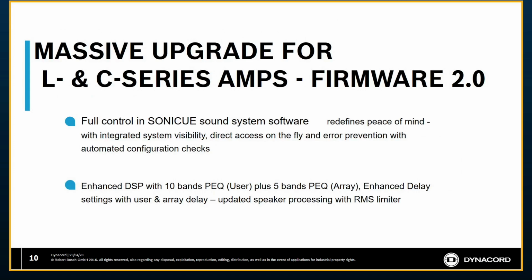For the LNC series, there's a new firmware update available where we have full control in SONICUE sound system software, and this redefines peace of mind with integrated system visibility, direct access on the fly, and error prevention with automated configuration checks. With this recent update, there's an enhanced DSP set now available for LNC. That's 10 bands of PEQ per user, and 5 bands for array, and of course enhanced delay settings with user and array delay. On top of that, there is some updated speaker processing with RMS limiters.